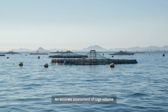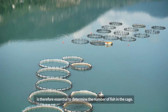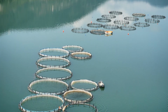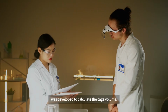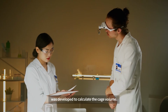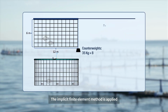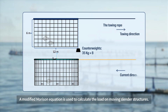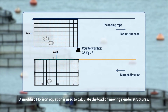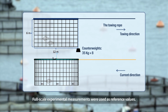An accurate assessment of cage volume is therefore essential to determine the number of fish in the cage. A numerical model based on the finite element method was developed to calculate the cage volume. The implicit finite element method is applied and line elements are used to model the structure. A modified Morrison equation is used to calculate the load on moving slender structures.